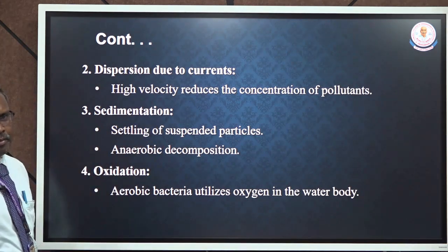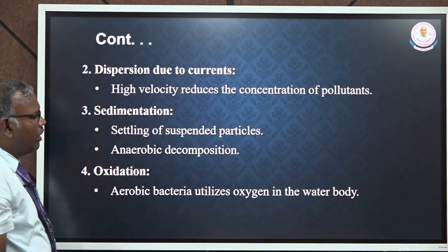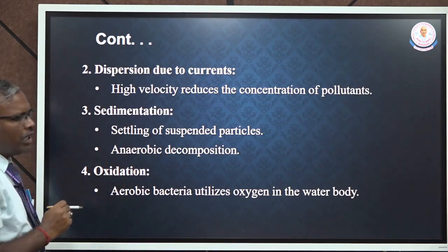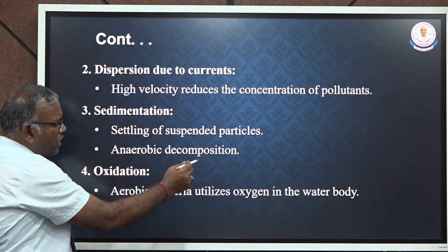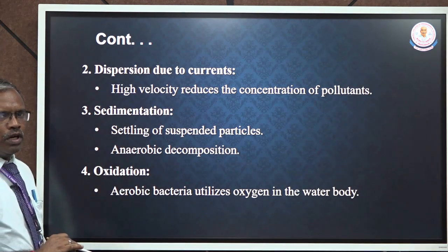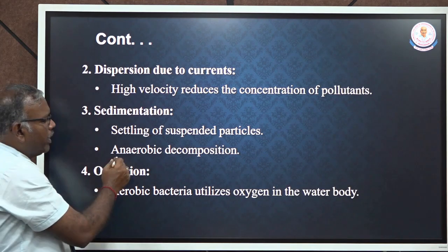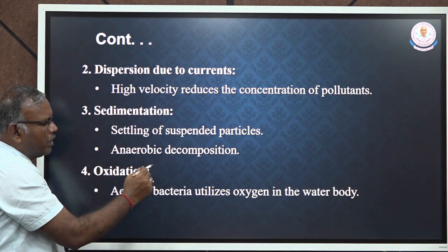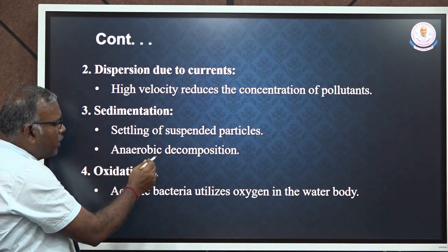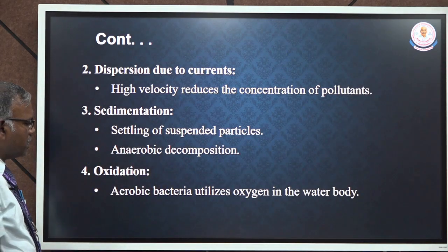Next, the settling will take place, where the suspended impurities will keep on depositing at the bottom of the water body, and it will be undergoing anaerobic degradation, that is in the absence of oxygen, because at the top of the water body the atmospheric oxygen transfer will be taking place. When the depth is above 1 meter, the atmospheric oxygen will not be able to penetrate, so it will be undergoing degradation by the anaerobic process.